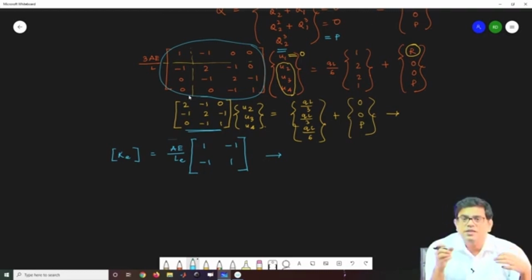So now this is coming mathematically. What is the mathematical interpretation of it? The stiffness matrix becomes singular unless you put appropriate constraints or boundary conditions. You will sometimes face this: if you do not constrain the structure properly, you cannot really solve it, right? So this will create an unsolvable problem unless you constrain the structure.